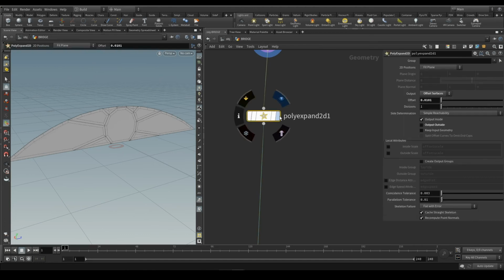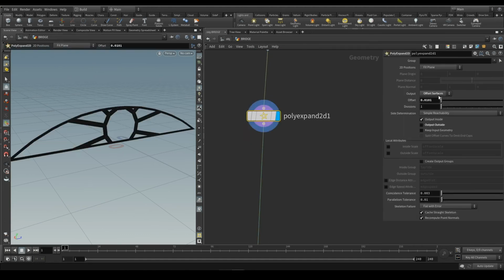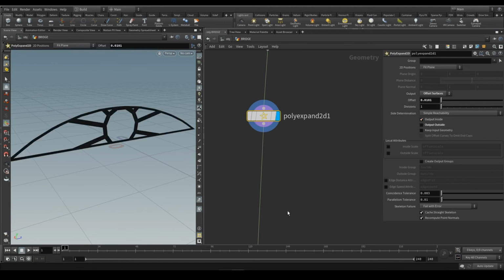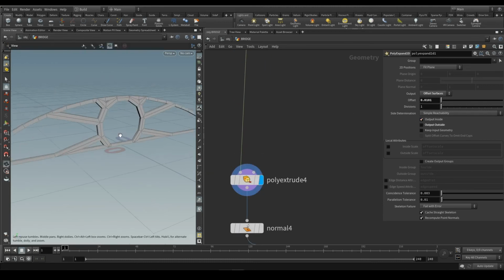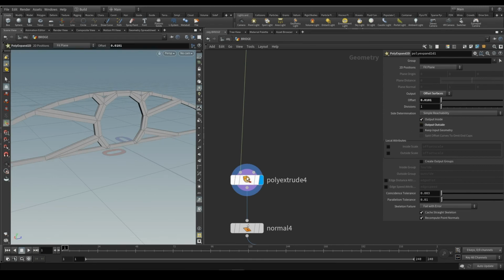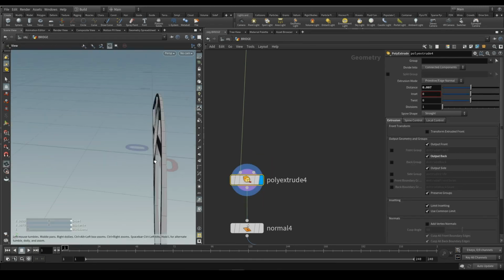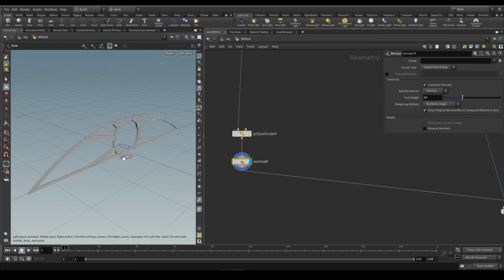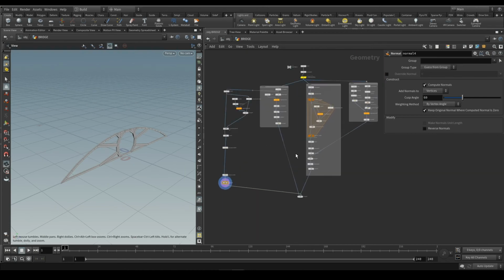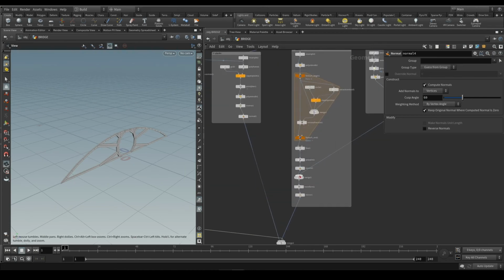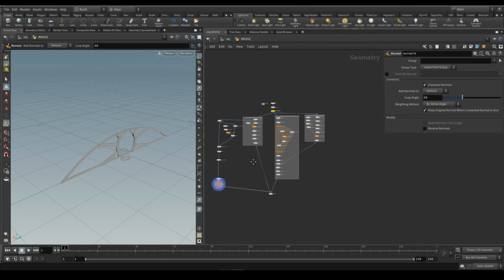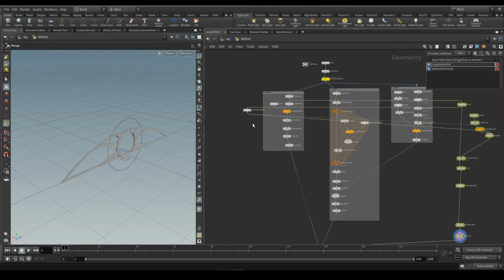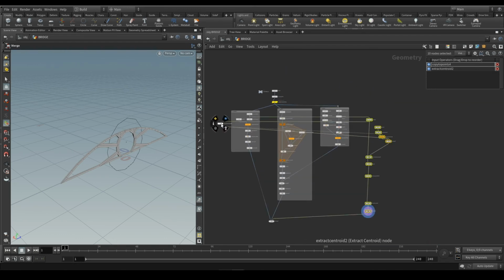Now use expand poly with the offset surface mode activated, keeping the inside geometry, extruding it with the output back checked, and bring it back. Its normals. Okay, and this is something that will be merged with sides, so I can push my node tree on the other side.